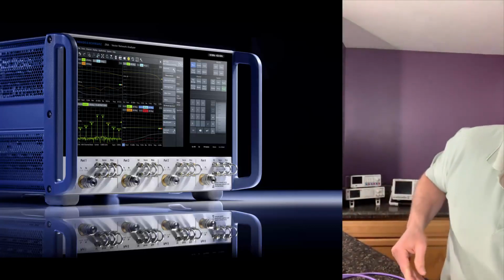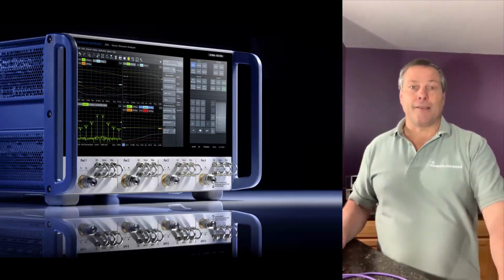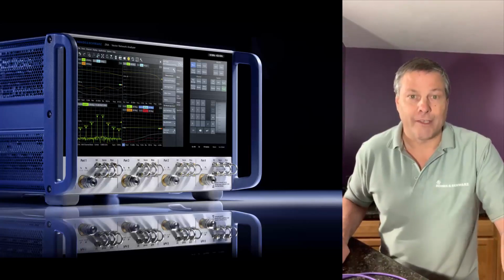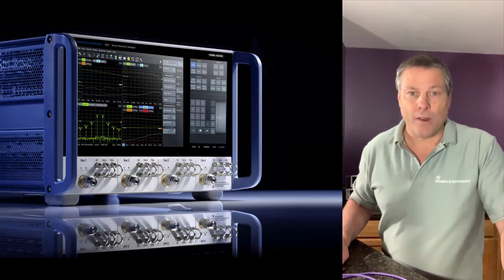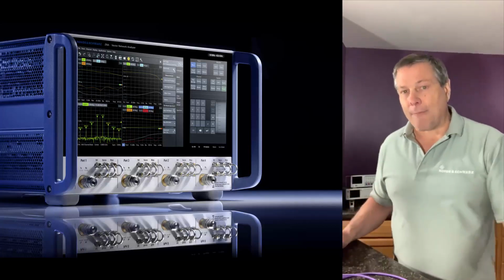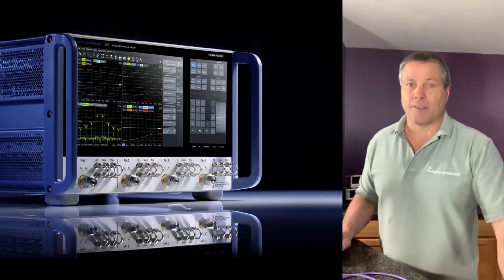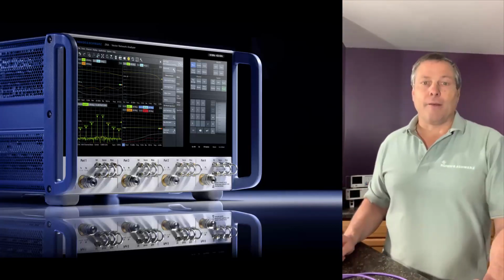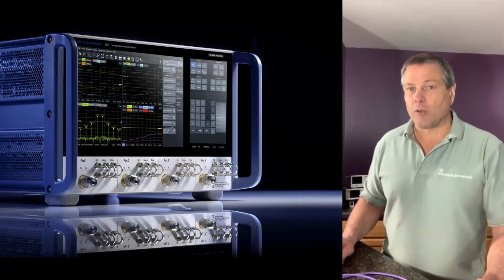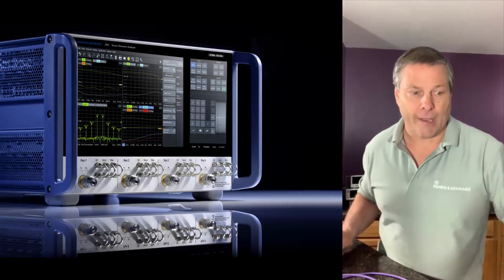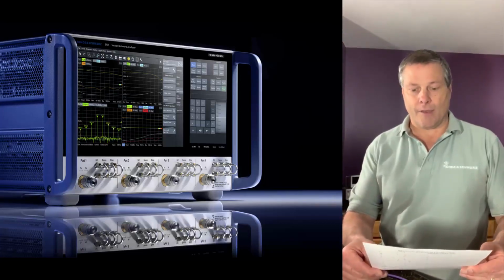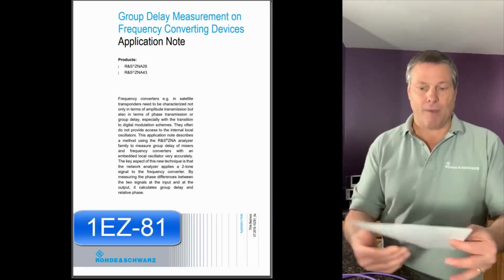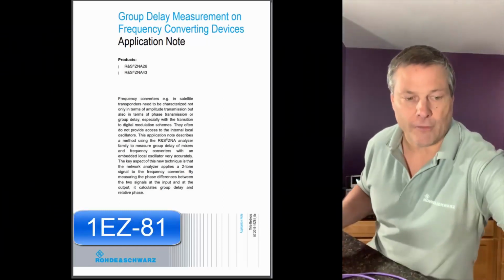For making a measurement like this, of course, I'm going to use the Rohde Schwarz ZNA vector network analyzer, which we introduced to the market about 1 year ago. This instrument has been optimized for making frequency converting measurements like this. In particular, I'm going to use option K9, which is our two-tone technique for measuring group delay on devices with embedded LOs. If you want more information on this technique, we have an application note, 1EZ81, which goes through all the details of making group delay measurements on frequency converting devices.